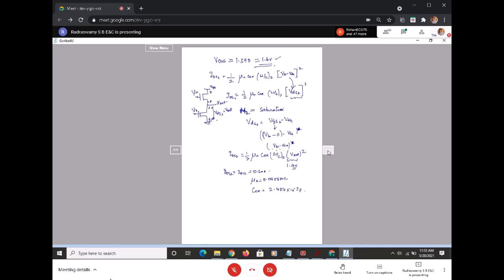Okay, so I know V out, I know what is COX, I know what is mu n, and I know what is my IDS2. I can calculate W by L2.